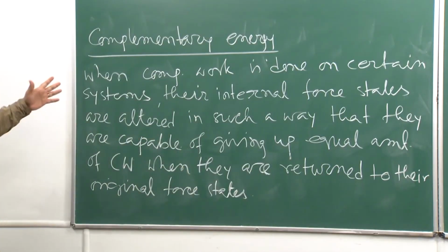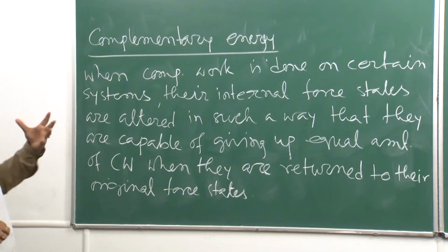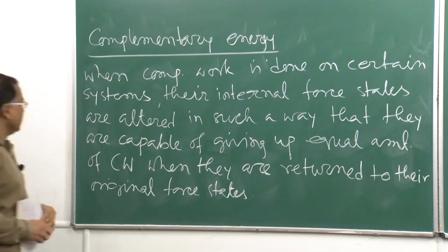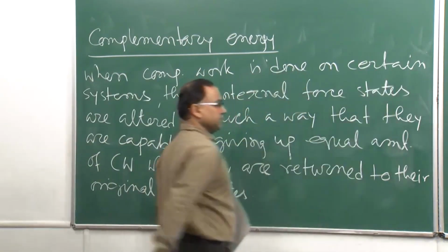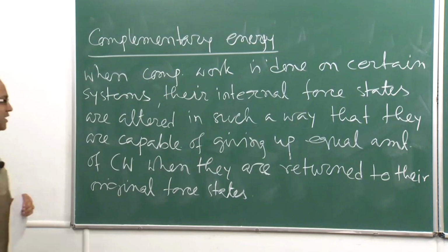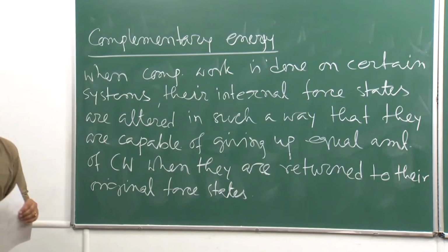Okay. So, when the complementary work is done on certain systems, their internal force states are altered, because when you do the complementary work, basically you are using the variable force and the internal force states will be altered. Gradually your internal force will be getting built up in such a way that they are capable of giving back an equal amount of complementary work when they are returned to their original force states.